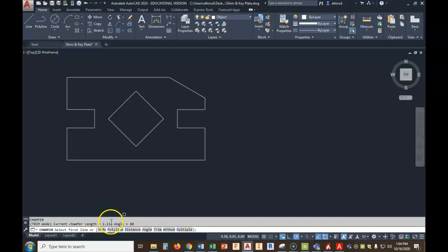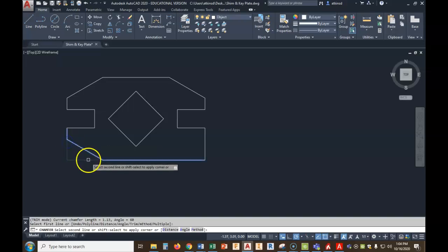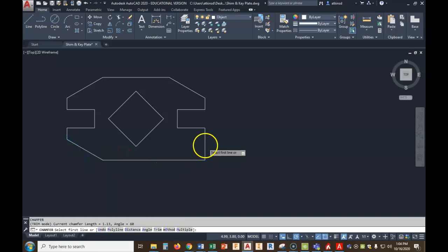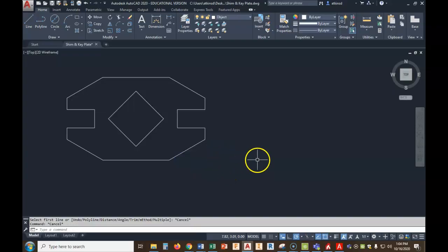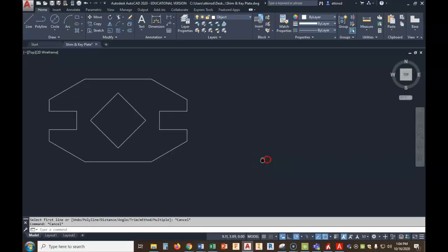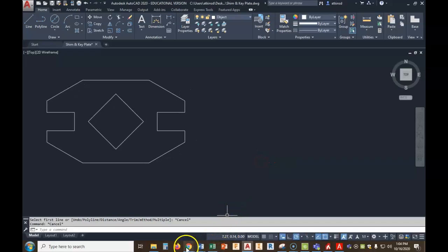Oh no, I typed in 1 1/8, 1.125, and it says 1.13. Remember, we have our numbers rounded to 2 decimal places. This is okay. It's still going to do 1.125. Again, I'm going to pick vertical, horizontal. Hit enter. Vertical, horizontal. Hit enter. Vertical, horizontal. And hit enter. Y'all, there's that drawing done. That one's finished, okay? So let's slide over and start the next one.